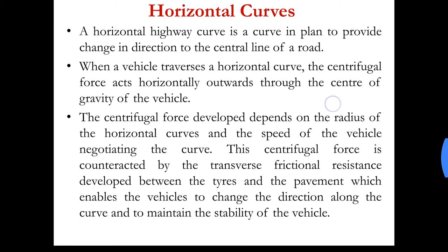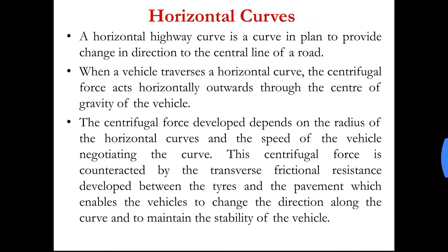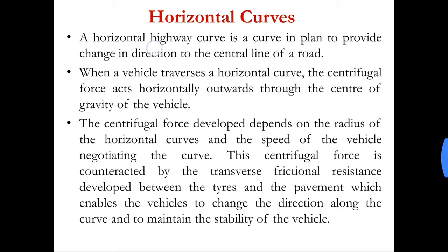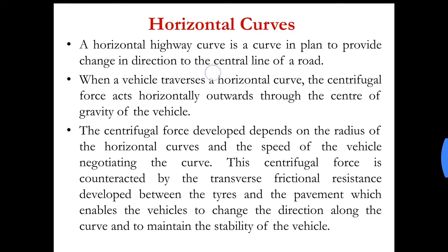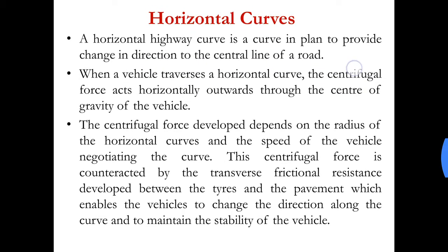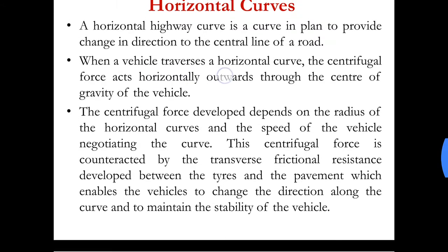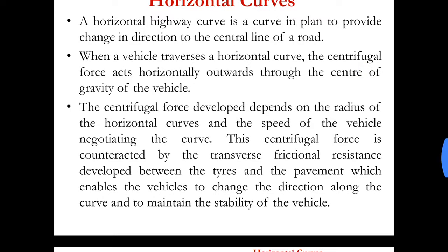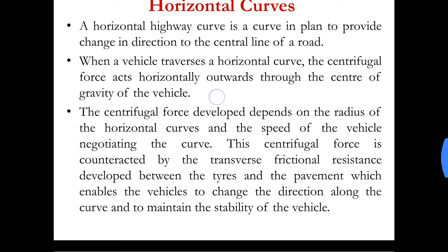The next geometric element that we design is horizontal curves. A horizontal highway curve is a curve in plan to provide change in direction to the center line of the road. So a horizontal curve is used to join two roads which are moving in different directions. When a vehicle traverses a horizontal curve, the centrifugal force acts horizontally outwards through the center of gravity of the vehicle.